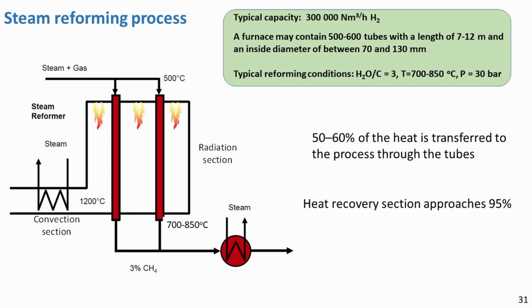The combustion of natural gas with air is accompanied by formation of nitrogen oxide. This becomes significant above 1400–1500 degrees C, which is easily suppressed in normal diffusion flames. The problem is solved by use of low NOx burners, and further reduction can be obtained by cleaning the flue gas using selective catalytic reduction.